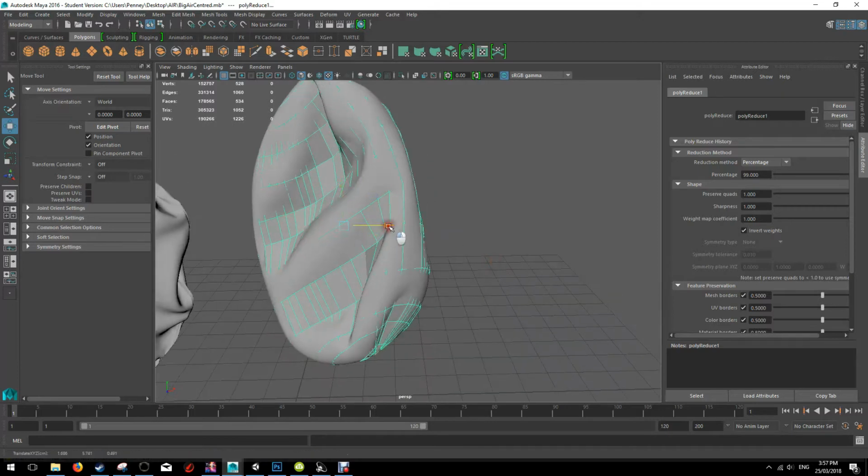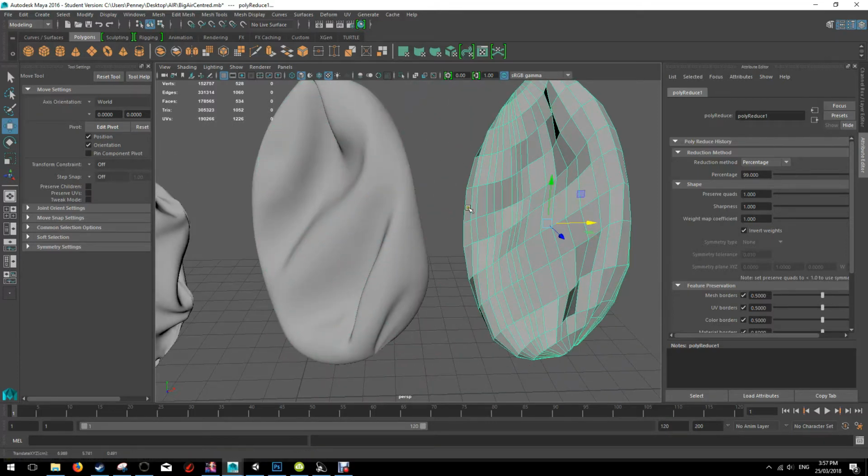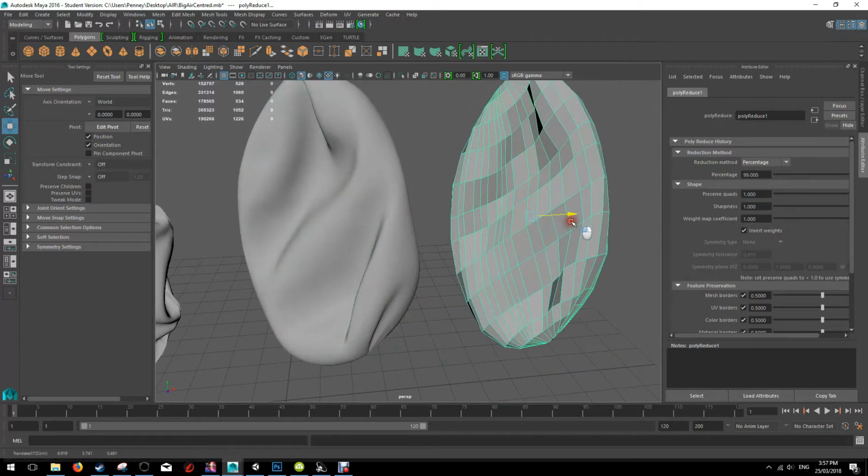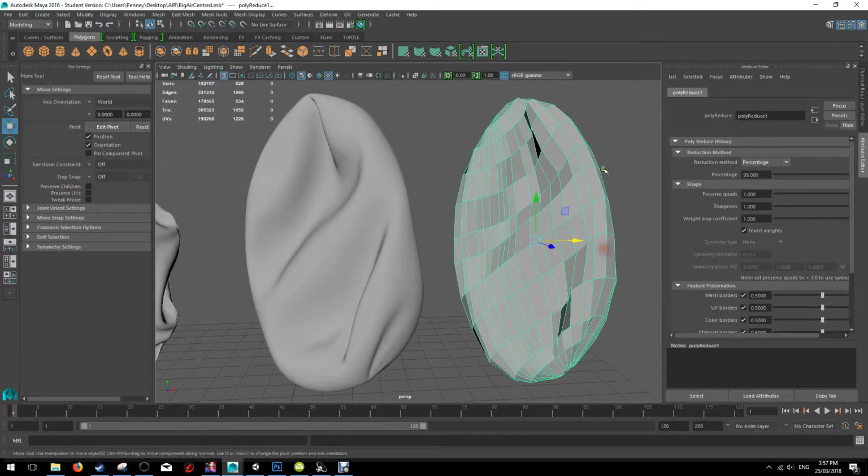So you've got your low resolution duplicate, and what's important here is that we're basically taking the lighting information on this object and projecting it onto this object, and that saves as an image file that uses the same UV coordinates as a texture file, except the colors on that image represent the direction that light should reflect off the object.